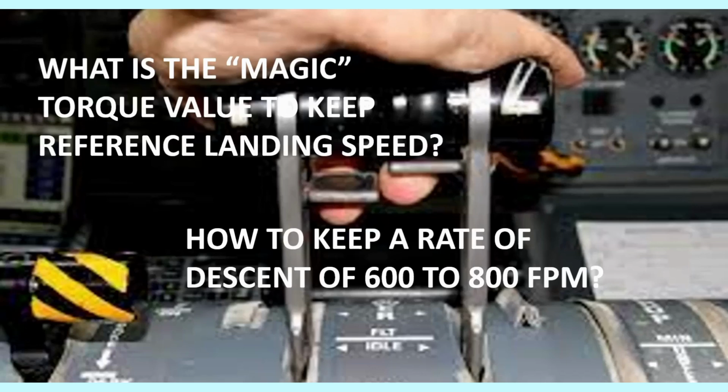In flight school and even in our normal everyday line flying, we normally know that we have to keep the glide slope centralized within 1 dot. Even if you are following a VNAV non-precision approach, we have to keep the VNAV bar at least centralized as well, and that automatically gives you on the vertical speed indicator a value of 600 to 800 foot per minute,